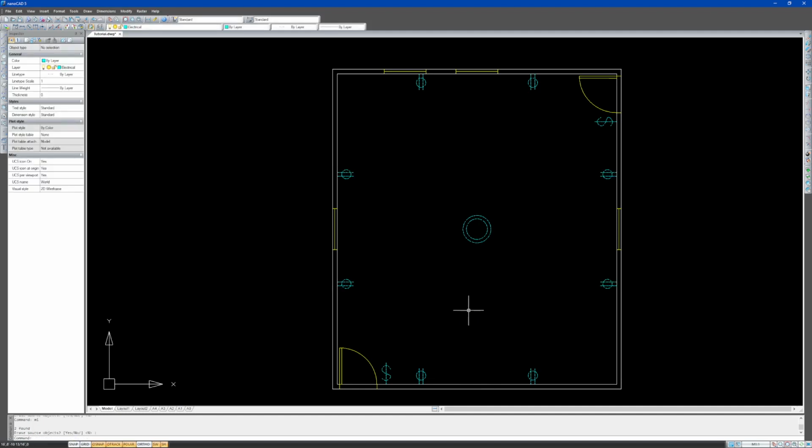Okay, the final thing we have to do is to link our switches to the light fixture. I'm going to sketch this to be a 3-way switch. In other words, you could turn the light on or off from either switch. So if you turn it on from here and you walk out this door, you could actually turn it off from this switch. And the way you do that, whenever you want to link your switch to your light fixture, you do that with the spline command.